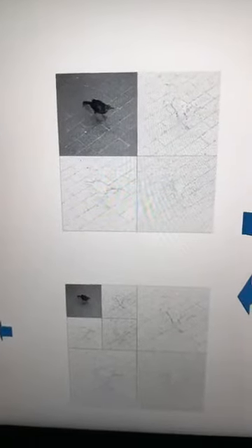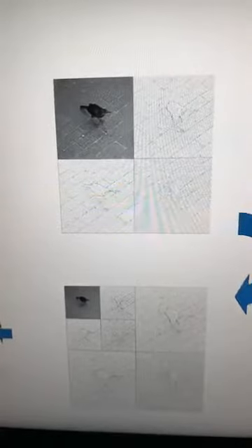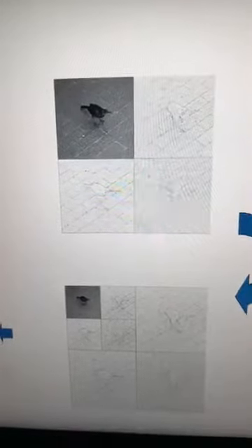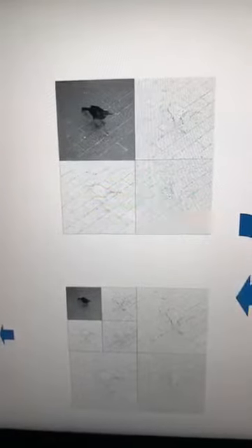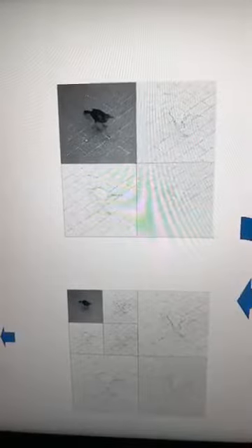So this is the image which you get after you pass it through a low pass filter on every row, then a low pass filter on every column, and throw every other sample. And remember, you are seeing 4 images, but just focus on the above image. Now you take this image and again do the decimation.